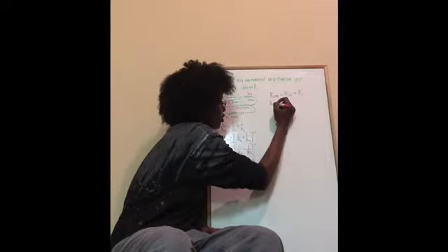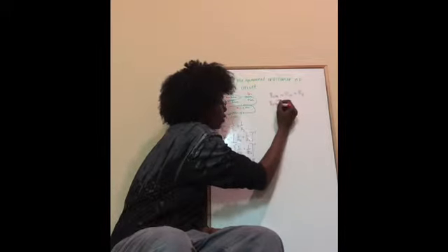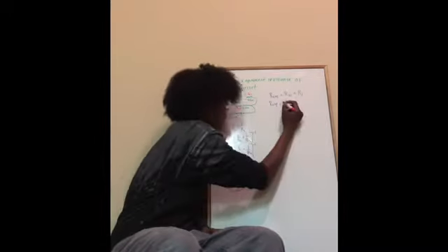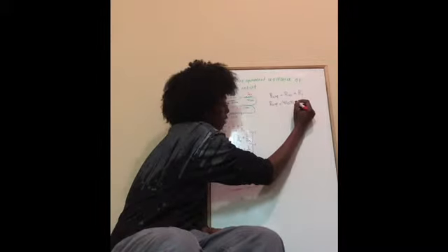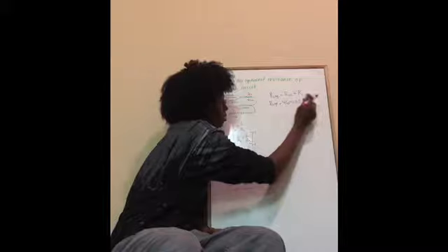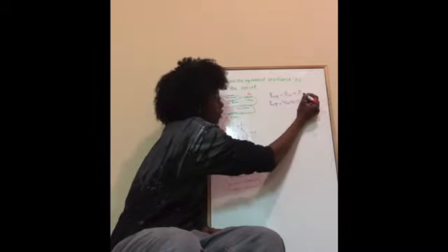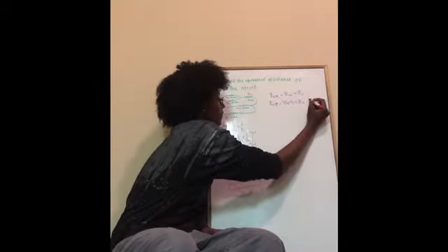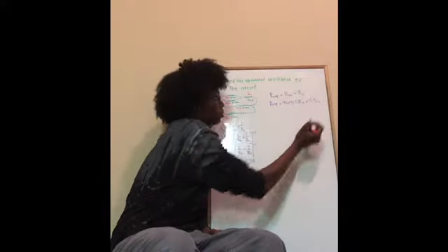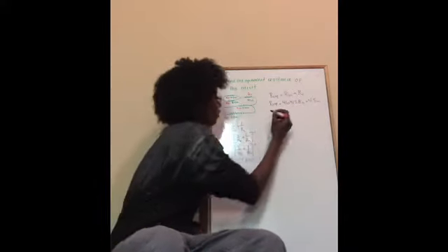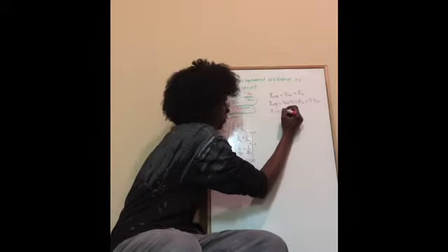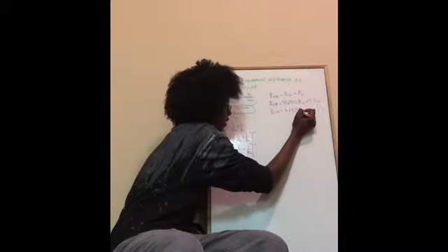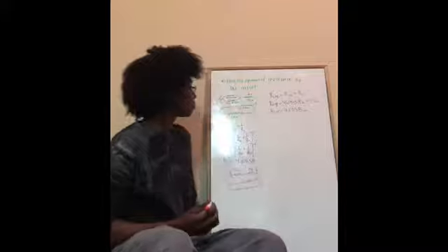So R2,3,4 is equal to our value now, which is 4.63158 ohms plus our R4, please excuse me, that was very ugly, which is 4.5 ohms. After solving for this, our R2,3,4 is now equal to 9.1358 ohms. Alright.